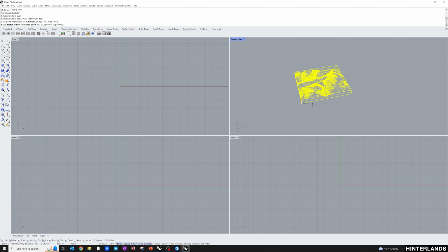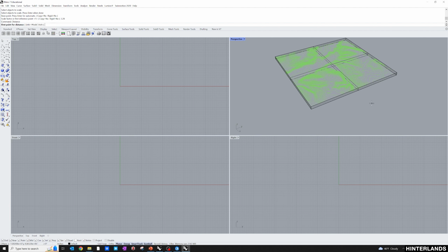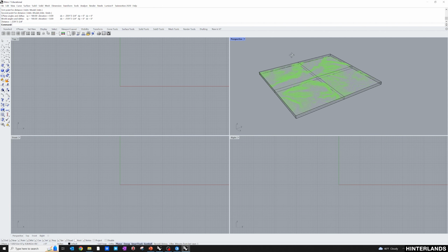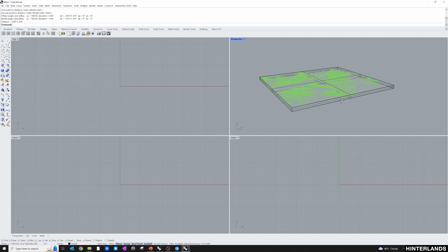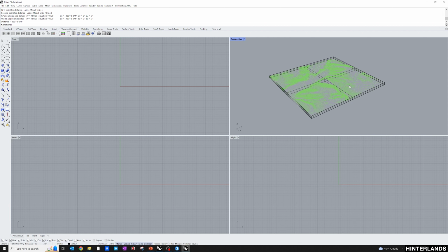We'll use this as our base point, and we're just going to go in one direction here, and I'm just going to type in 3.28 and hit enter. Don't need to hit it again. And then just to verify the distance here, we've got 2,591. So it's more than what we put in ArcGIS, but it's possible that something got adjusted in that process of drawing the polygon. It may have had something to do with the way that it drew that polygon in the coordinate system in the file. So I think for our purposes, this is close enough.